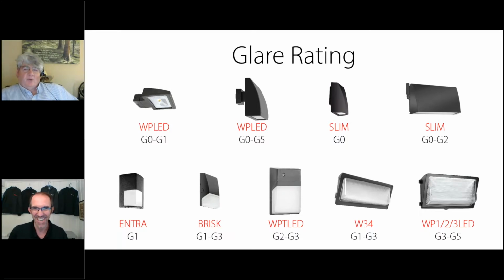We should always care about glare. As a matter of fact, I think it was a couple of years ago, the president of the IES said that we've got enough lumen output now, glare should be our number one concern. However, there are times when there are overriding factors. But my preference is always for full cutoff area lights versus floods, full cutoff wall packs versus non-cutoff wall packs.